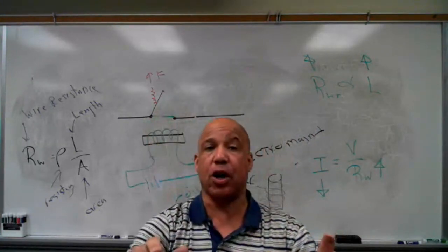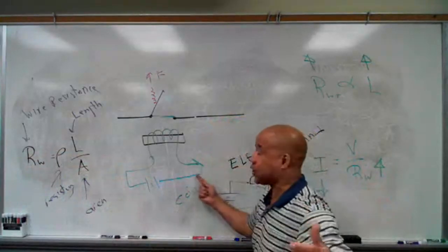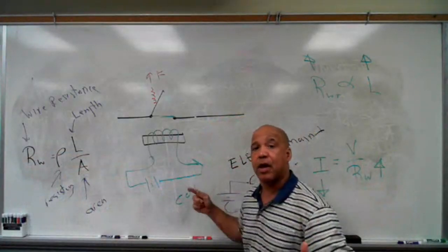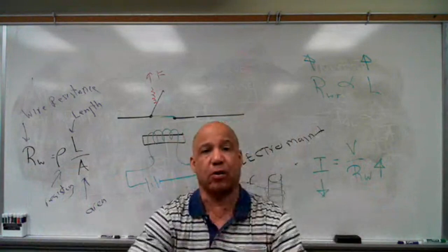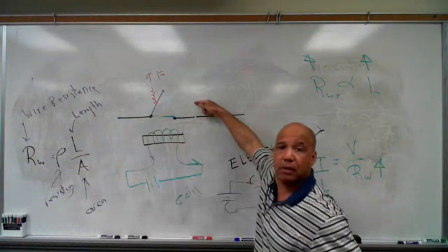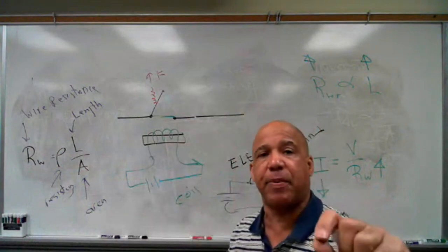This is exactly what you do when you start your car. You put your key in the ignition and you turn the switch. What you're turning is this one. That's a low current circuit. But the starter motor, which might need 10 amps to get the engine turning over, that's this circuit. Separate circuit.